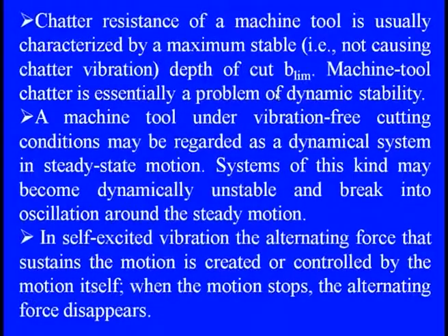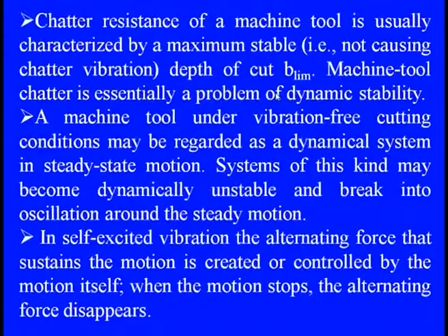So, the chatter resistance of the machine tool is usually characterized by a maximum stable depth of cut. We look at how much depth of cut there is, and accordingly the chatter resistance comes out, or we can say the chatter vibrations are. And the machine tool chatter is essentially a big problem of dynamic stability for this machining feature.